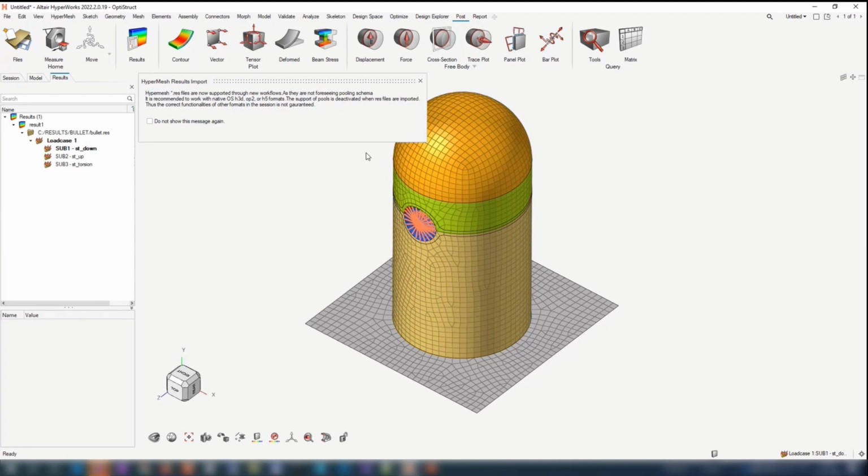In this case, the REST file doesn't have it, so we are tweaking the underlying infrastructure to support the absence of ID pools and showing a little warning message to say that there could be some hiccups on the OP2 or H3D that you're going to load if they also have ID pools. Actually, I've been testing pretty thoroughly all the several options.